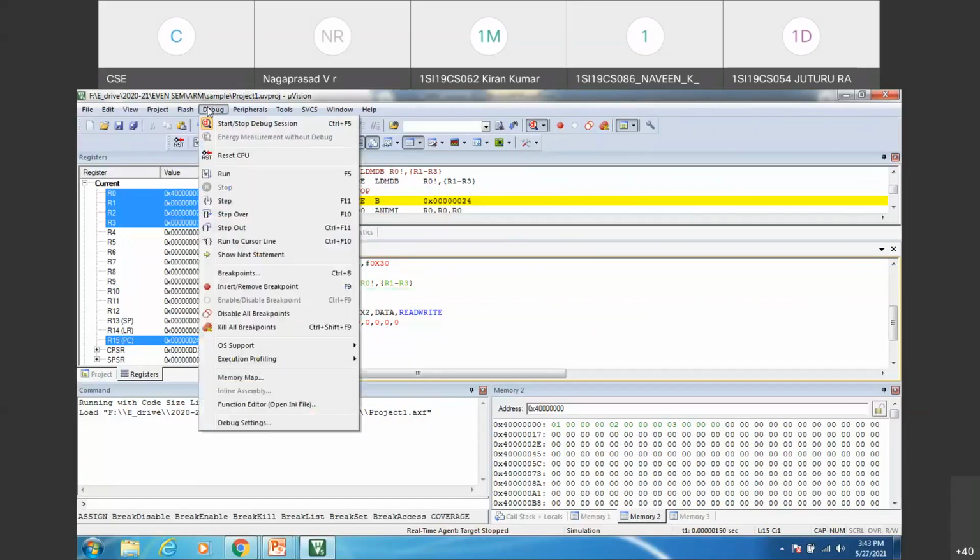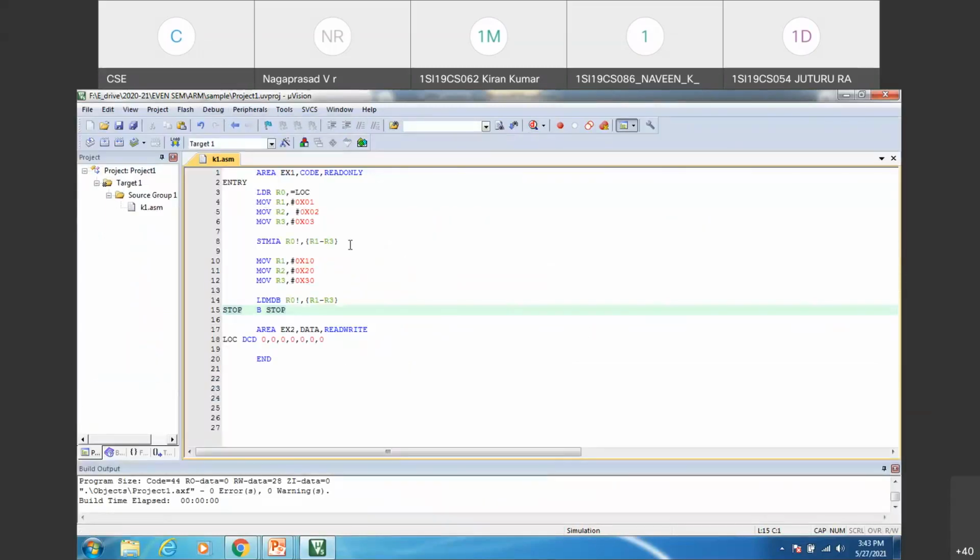So any order you give in the register list, say I'll give it as R3, comma, R2, comma, R1, whatever the order you give in the register list here, if it were IA addressing mode you are using, then first it is going to save R1 content, then R2 content, and then R3 content. So from lower address to higher address, if you are moving from lower register to higher register, the data will be taken. Is this clear?